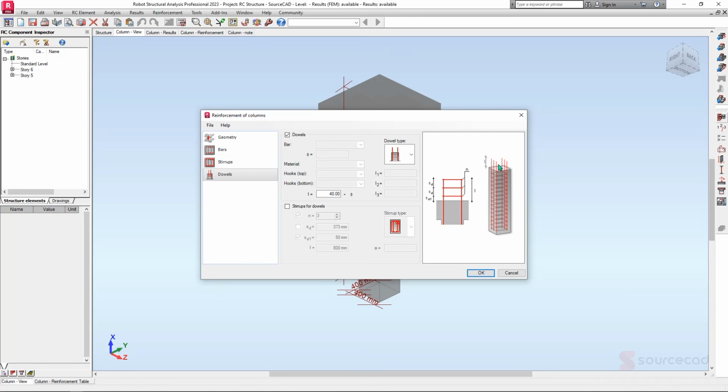Under the dowel, this is just the elongation. You can specify the type that you prefer. So this is an extra reinforcement, is quite long, or you can use this overlapping system where you use one bar and then you cut and then you overlap again. Either system works, depending on the one that you prefer. So this one, let's say we use D20 as well.